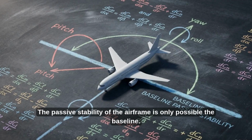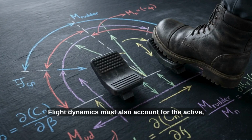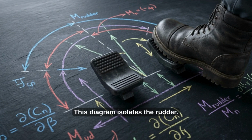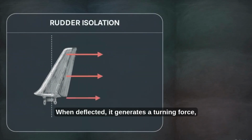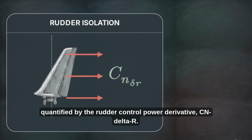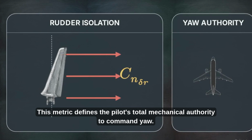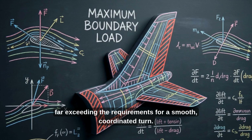The passive stability of the airframe is only the baseline. Flight dynamics must also account for the active, intentional forces of directional control commanded from the cockpit. This diagram isolates the rudder. When deflected, it generates a turning force, quantified by the rudder control power derivative, Cn delta R. This metric defines the pilot's total mechanical authority to command yaw. Engineers size the rudder to survive worst-case asymmetric boundary conditions, far exceeding the requirements for a smooth, coordinated turn.